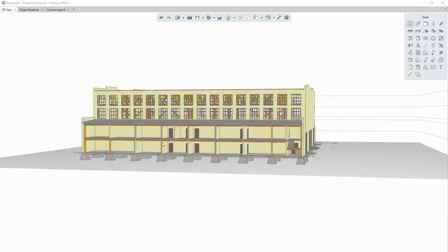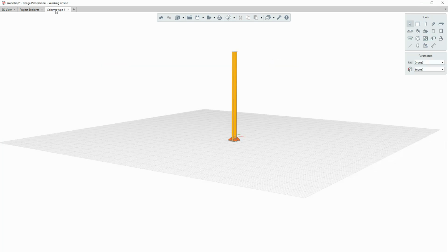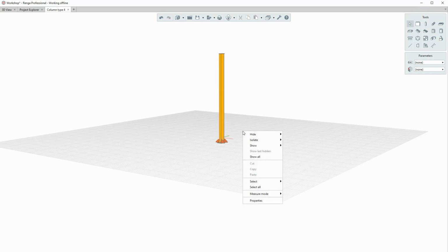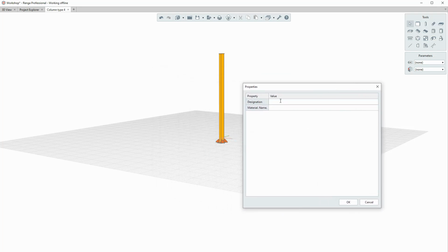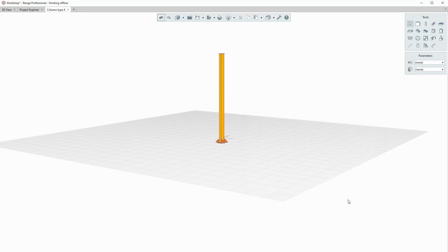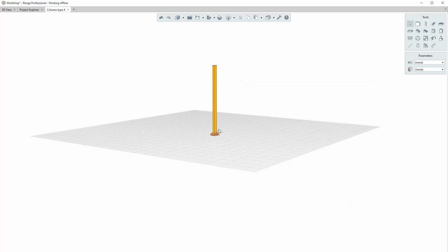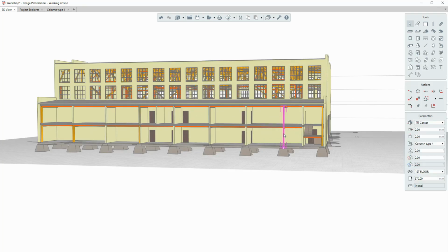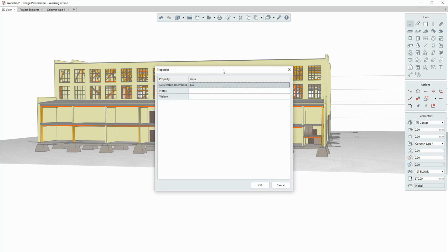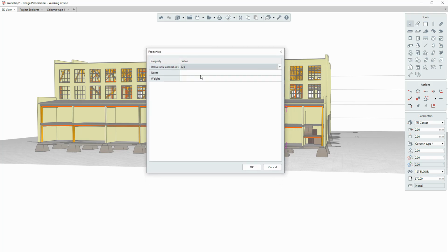Finally, we fill in the properties we have added for the assembly styles and for the assembly instances located in the model. To assign properties to the assembly style, in the Assembly Style tab, right-click to open the context menu. Select the Properties command. Type a value in the value text box. Click OK. To assign properties to the assembly instances located in the model, select any assembly in the 3D view and use the right mouse button to go to the corresponding menu. Then add the required information.